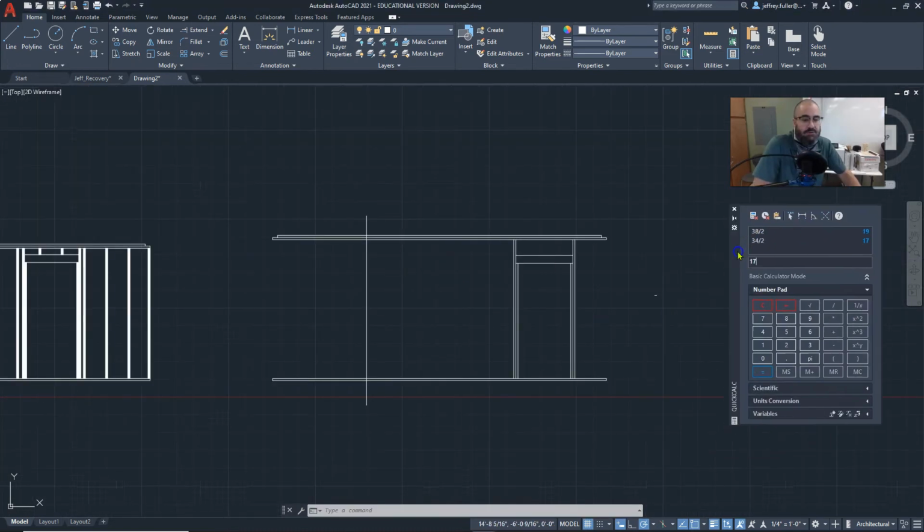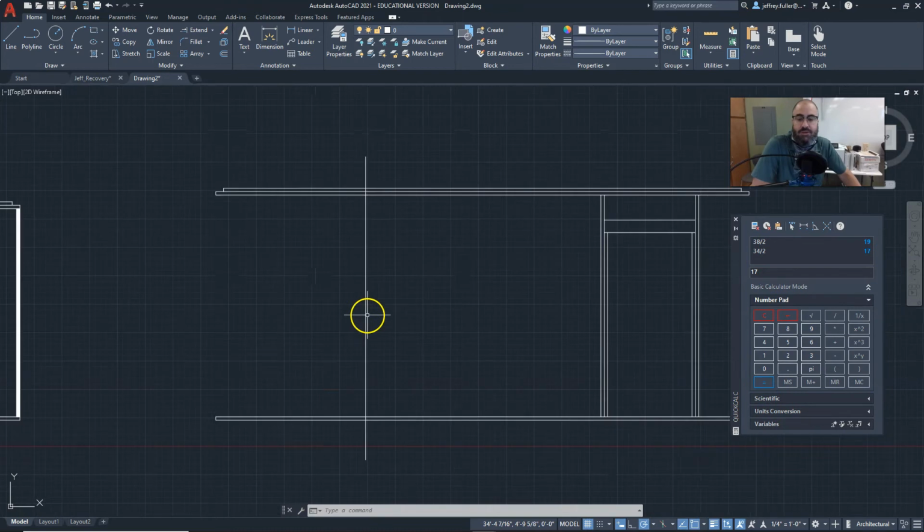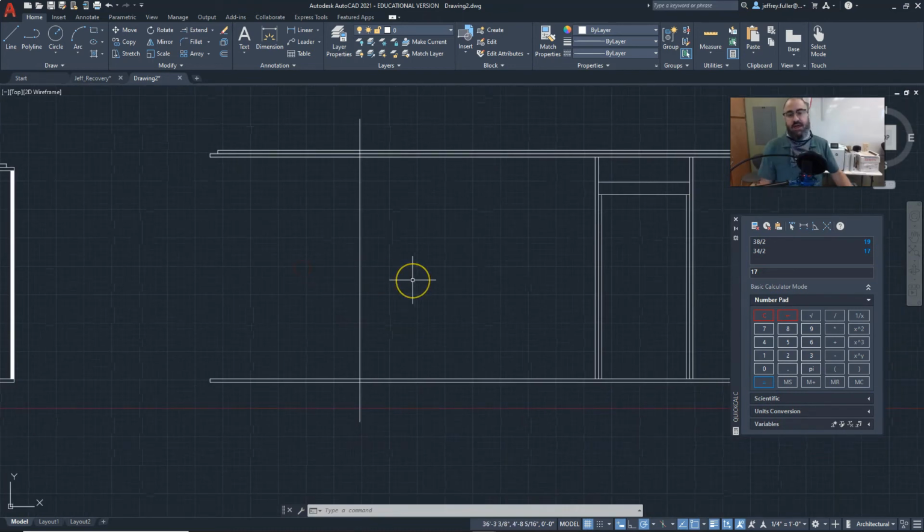Okay, now we're going to do the window. Let's say I got a 34-inch window from the store and I'm going to install that. So I need to include a couple extra inches on each side to have some wiggle room, just like the door. And then plus I want to mark my king studs with this first offset. So I'm going to add 1.5 inches to that offset.